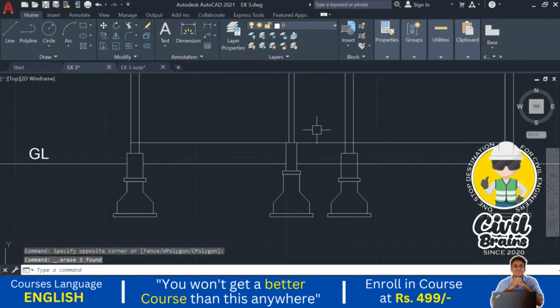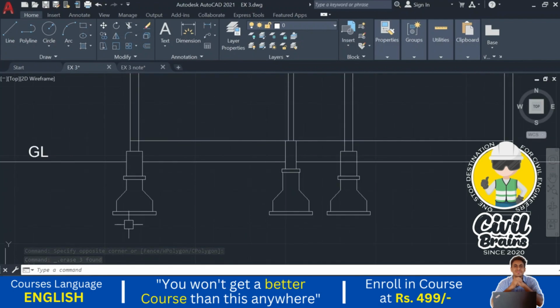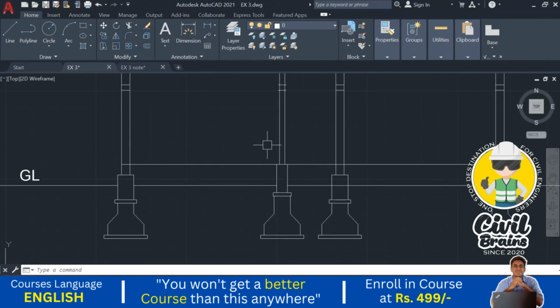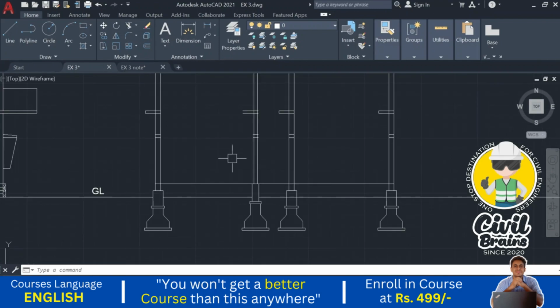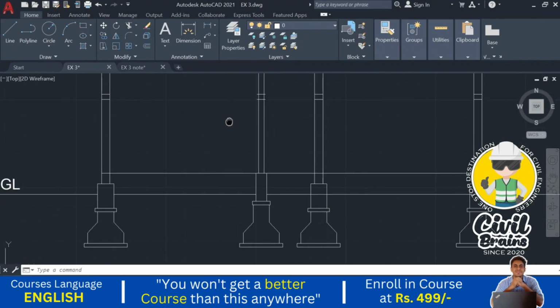Okay, here you can see the difference: here it is PCC footing, and this is the column, after this is the isolated footing and this is the column, then again PCC of the wall and the wall foundation, and above the wall foundation there is a plinth beam, and above the plinth beam there is a wall, main wall. Here PCC, isolated footing, the column, the PCC of the wall foundation, the wall foundation, there is no plinth beam on the partition wall, and the partition wall is of thickness 0.15. Okay, and above that one lintel, and it will continue over here. Okay, clear? So we have done it here.